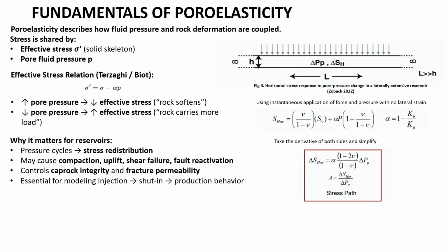If we look at the results, we would see that if you plug those values in, the horizontal stress is changed by 2/3 of the pore pressure change. In this case, the vertical stresses do not change, so only the horizontal stresses respond. A practical example: if the pore pressure decreases by, say, 6,000 psi, then the horizontal stresses would decrease by 2/3 of 6,000, which is 4,000 psi.